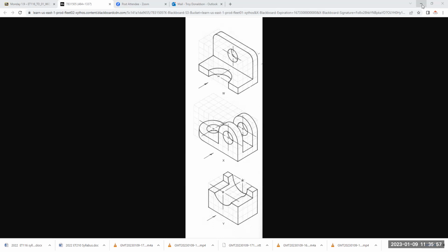Dimensioning is looking at that scale. So if I don't change it, it's going to go 1:1, 1/8 inch, and then it's going to reduce it 5 times to, I can't even see it on the drawing, right? So I go here and say 1:5. You've got to commit to this because you don't want to get 3 hours into dimensioning and then realize it doesn't fit, because now you've got to, oh God. It's all changeable, but it's a big pain.